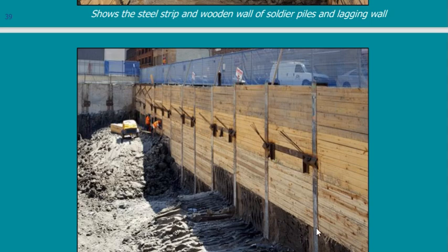So to these soldier piles with wooden lagging, I added a level of anchors. So instead of just drilling maybe 10 meters, I can drill 20 meters with this system, 30 meters, maybe adding another level. When I go deeper, I put another level here of anchors, and so on till I reach a very great depth below ground.